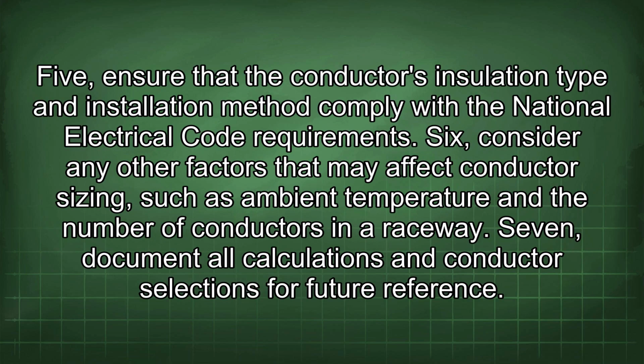5. Ensure that the conductor's insulation type and installation method comply with the National Electrical Code requirements. 6. Consider any other factors that may affect conductor sizing, such as ambient temperature and the number of conductors in a raceway. 7. Document all calculations and conductor selections for future reference.